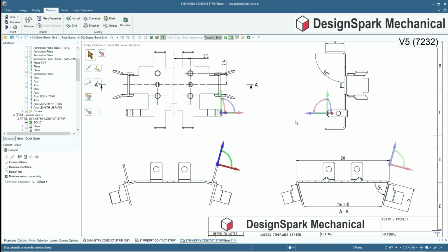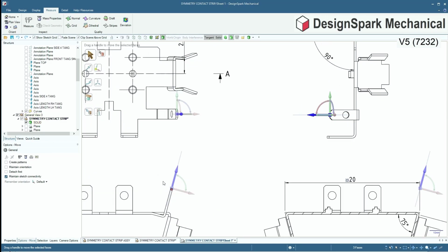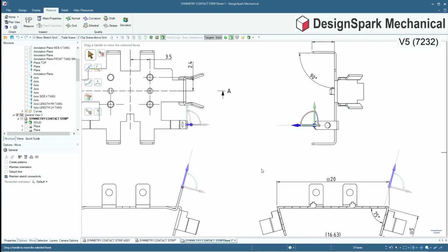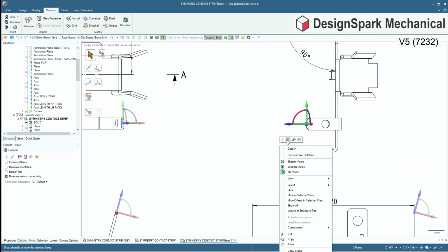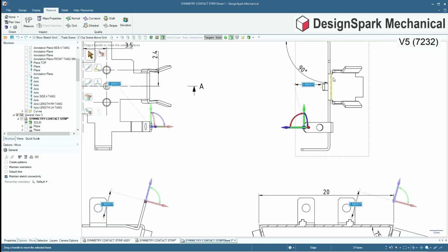So another interesting thing just quickly is that you don't have to choose this particular move tool to move. If I chose that direction up there, that direction now becomes more solid with the other ones moving into a phantom mode. I can right click on this and still choose the ruler dimension. And the interesting thing is that I can now select any point on an edge.